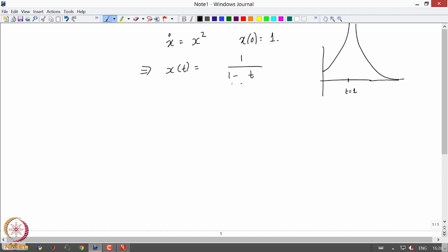Okay. Now is this a stable behavior? Well, this is not, right, because the solutions actually go unbounded. So what was the definition of stability? That whatever the solutions do, they should just be bounded above by some number. Okay. This typically could happen in some nonlinear systems, and this phenomenon where at t equal to 1 the system blows up is called the finite escape time.